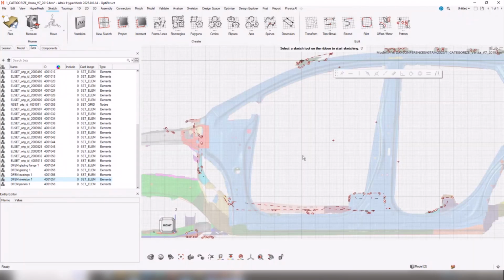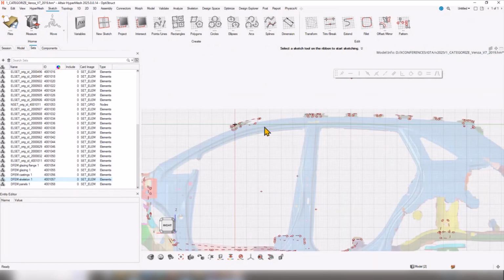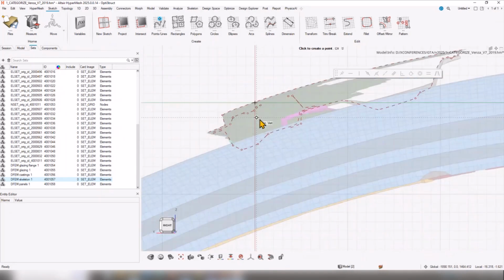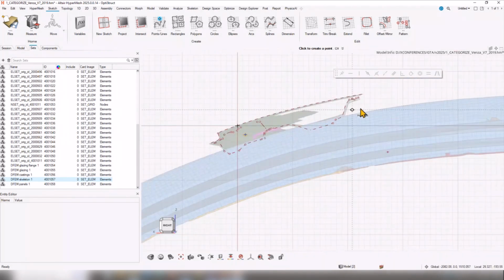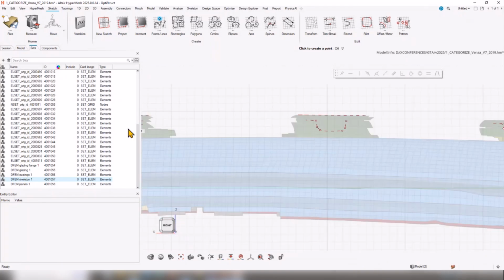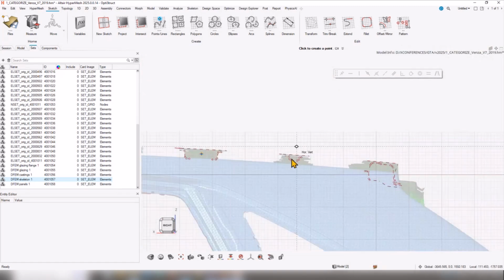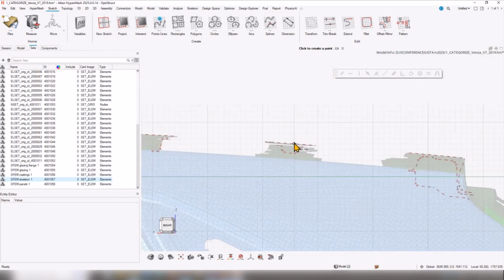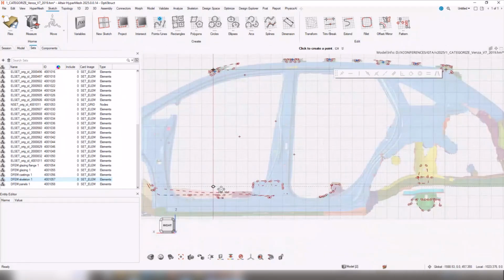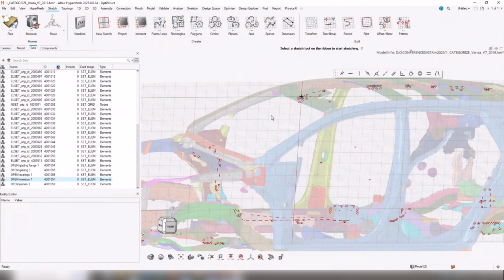so that's the junction I'm working with right now, the section plane. So I know that I need to have a point along this section to do that interpretation. So under point now, I'm going to click here because I know that this is a bunch of noise here that I don't want to include in my interpretation. Let's just say I want a point here. Maybe that was a misclick here. So I'm just doing this very quickly in the interest of time. But you can see that I can build out this profile definition. I won't do the rest now. Very, very quickly, I would need to do this at the front, obviously, and right the way around, but I won't do that now.